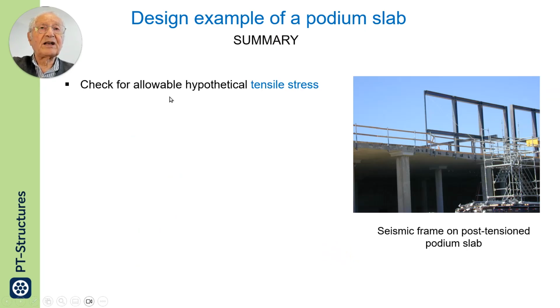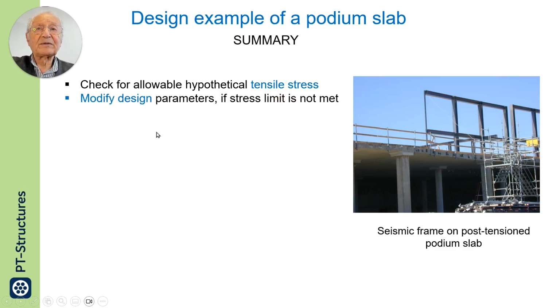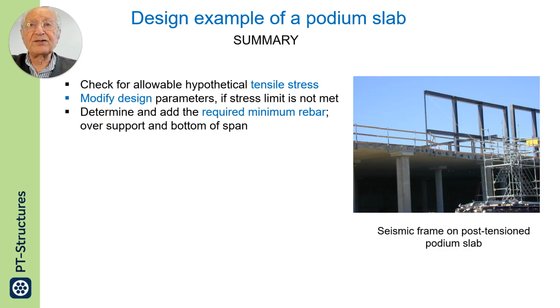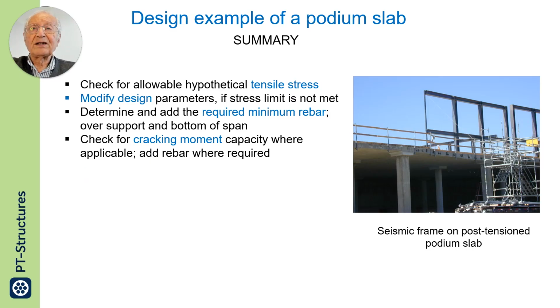We checked the hypothetical tension stress. That was a mandatory requirement. We modified the design where stresses exceeded, but in our case they did not. We then moved to minimum rebar requirement. The code says you have to have a minimum bonded reinforcement, irrespective of other considerations. Then we check for cracking moments where applicable.